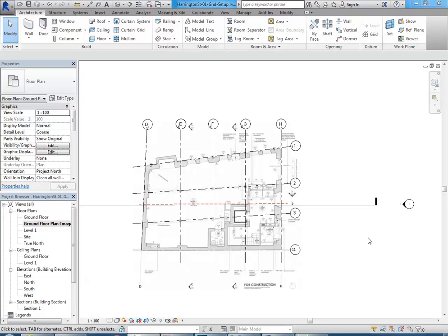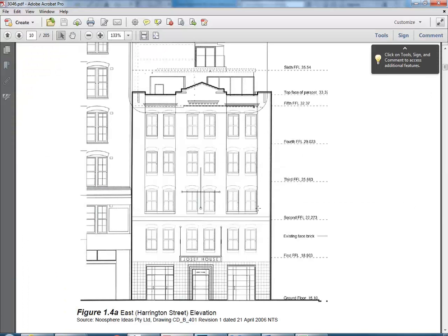And I'd have to go through hiding that elevation reference in every floor plan, and it's a lot of extra management that you maybe don't need to do if you just read off the values, because all we really need here is the level heights, and we can just refer back to this and then type them in as we go. So don't automatically just insert everything that you need if it's not worthwhile. And again, especially elevations and sections, I find often it isn't really worth it.